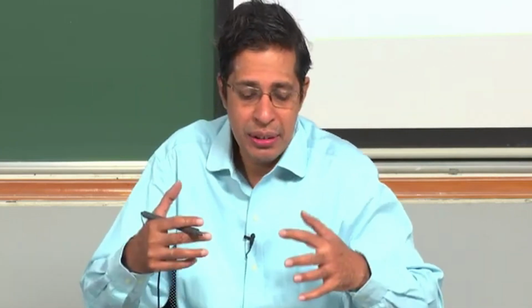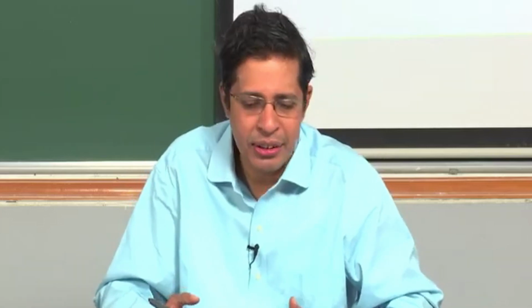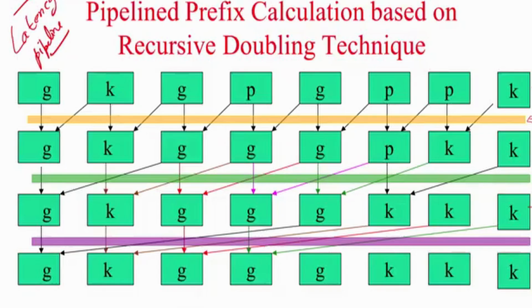So, the basics of the intuition for pipelining comes because when I do not have these storage stages, after this first stage finishes processing the data, it waits for the remaining 3 cycles for the entire computation to finish. Unnecessarily it is holding the data, correct. And similarly, when the first, third and fourth are processing, the second one actually is idle.